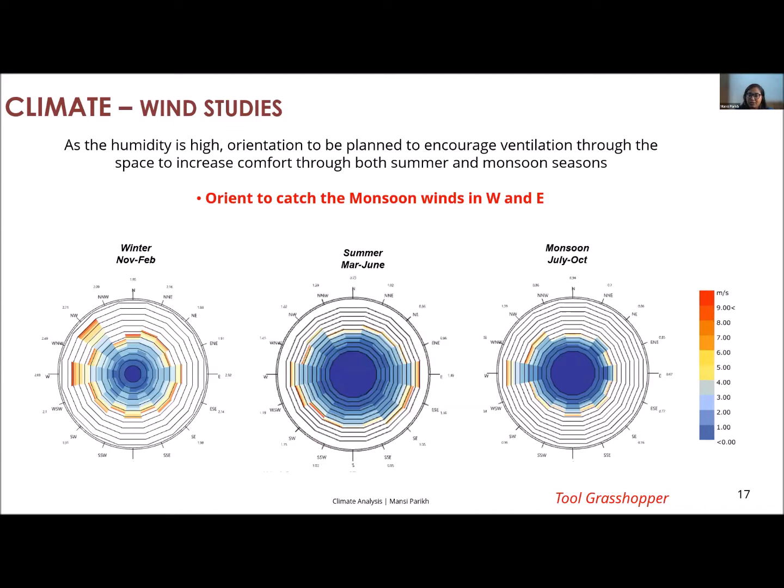In this project, we cross-ventilated the corridors and the classrooms specifically for the monsoon months, because in monsoon we have higher temperatures and higher humidity. So we wanted to ventilate these particular spaces for the monsoon months. We ensured that the wind flow had an inlet as well as an outlet for better flushing of air in the space. So windows were placed in the west, east, and northwest directions to improve the wind flow in the space.